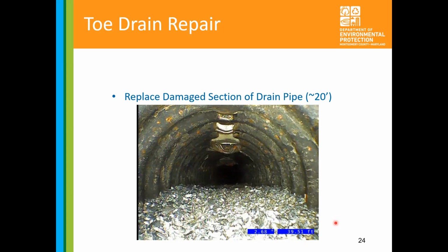I don't know if you all saw the very last question that popped up about the 15-foot restriction on woody debris at the toe of the dam embankment and whether that extends onto other properties. Do we know if that extends off the parcel? No, it stays on the current parcel. It is extending close to the property line, and the reason is we are putting a drainage swale at the bottom of the embankment.